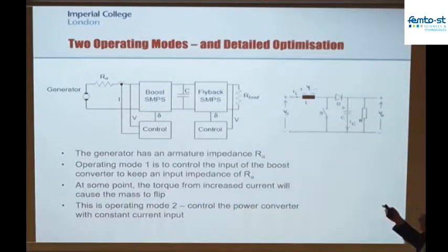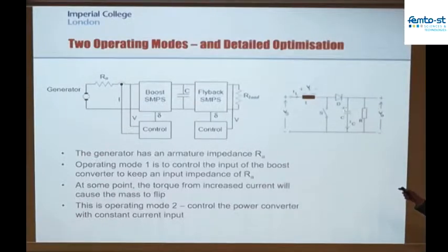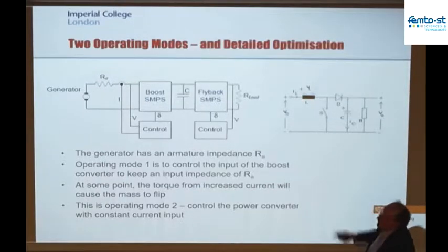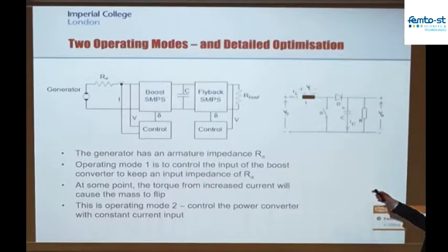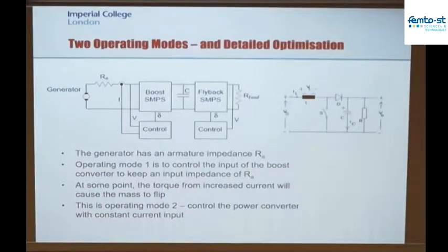You've just seen these switch mode power supplies. This is the boost converter, the second of those switch mode power supplies that we just looked at. I said to you on numerous occasions, things we can control in power electronics are voltages on capacitors. That's very useful for a power supply to be able to control the output voltage of whatever we're supplying something to. The other thing is controlling a current in an inductor. And there we are. On the input side of this converter now, we can control the current in that inductor. So we could measure that current, and if the current needs to be bigger, we increase the duty cycle of the switch. If it needs to be smaller, we decrease the duty cycle of the switch.